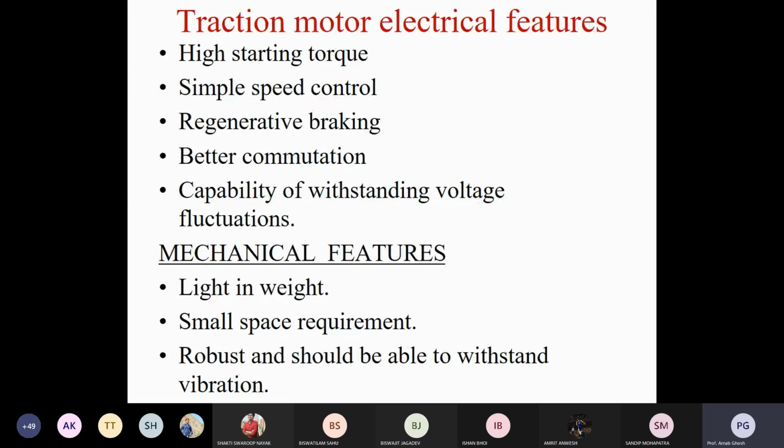Then your other motor is also rotating at the same speed, the base speed. If you see the tachometer value, you can see that both tachometer values come to the summation of both rpm. Then what you need to do is go for field control on the driving motor. It is a same rated motor, so the same speed is there, and now you are going for field control.